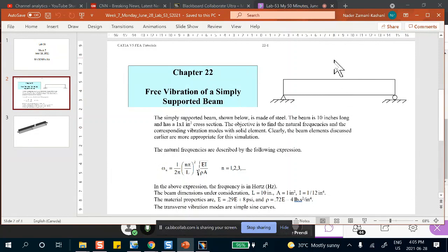This will go up and down and up and down at a certain frequency. There is no force applied. The only thing that you did is apply a force to move it off balance, basically, and then let it go. That is what free vibration is. Now, in the real world, that will not go indefinitely. At some point, it will stop. The amplitude of this going up and down gets smaller and smaller, and that's because there is damping involved. We are not living in an ideal world.